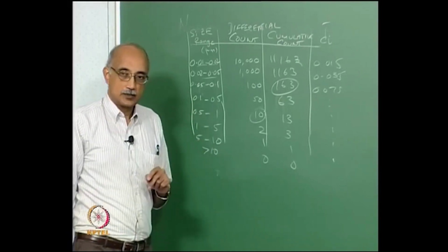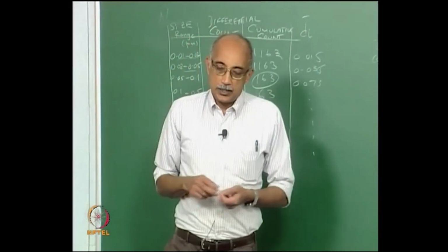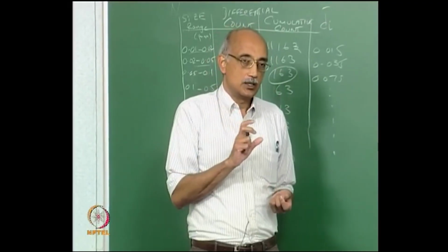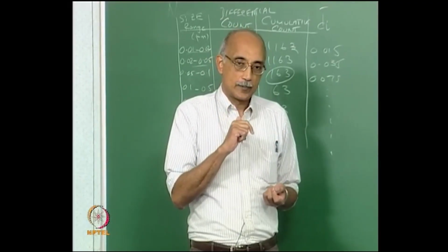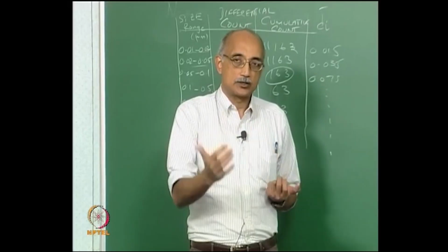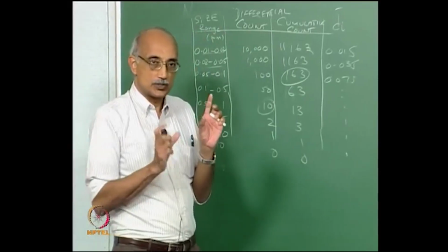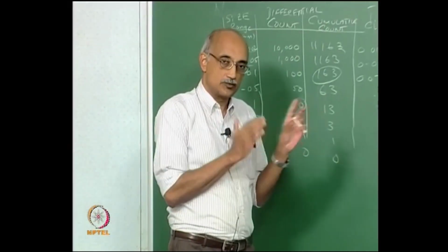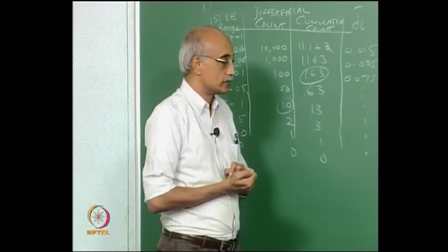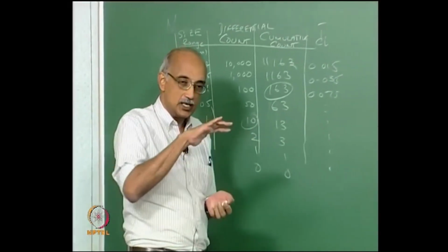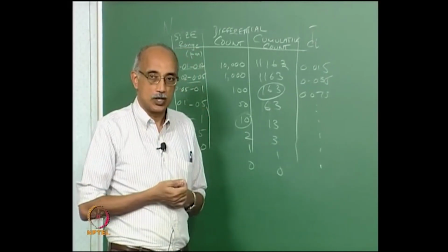And the reason for that is, again, particularly in a log normal distribution, the changes that we see in the particle counts are extremely high at smaller sizes compared to larger sizes. So the relative sensitivity of counts to size is much greater in the finer fragment of the population compared to the larger fragment of the population, and that is why you need to have as fine a division in the small particle size scale compared to the larger particle size scale.